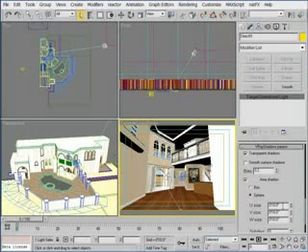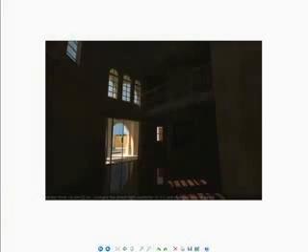and I need to increase the UVW size because the default values will be too low to have an effect. I know from experience that a value of about 3 feet works well, so that's what I'll use here, 3.0. With this change, the rendering looks like this.